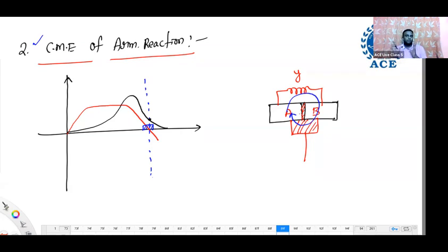So during that condition, if the EMF in the coil is very high, the current is also very high, which may sometimes damage the commutator segments and brushes with heavy spark. Now, along the brush axis here, what is the magnitude of flux due to armature reaction? One of the effects is the cross magnetizing effect. Due to this cross magnetizing effect, the flux is not becoming 0.